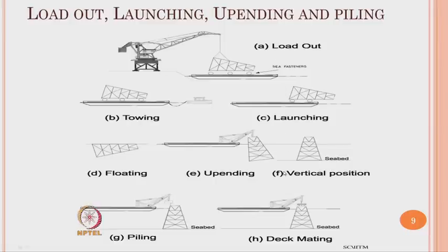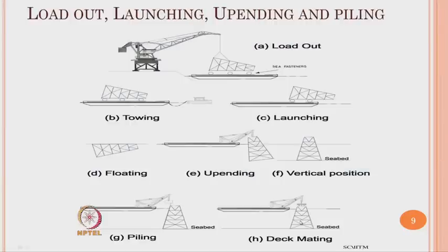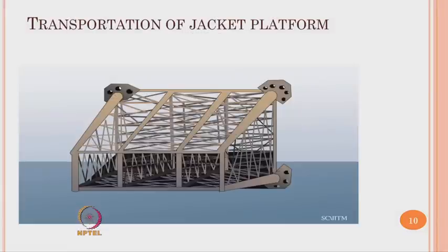As we all understand, dynamic analysis becomes important not only during the load out stage, but also until the deck mating is done. At different stages, different kinds of forces act on this platform, and the platform must be designed or analyzed for these kinds of dynamic variations as they are encountered from the varieties of forces acting on them. This picture shows you a clear transportation of a jacket platform.